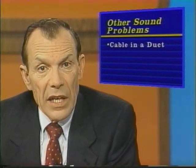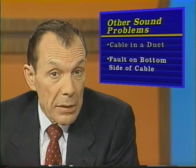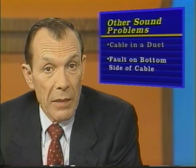Remember that sound waves travel out of the cable at the exact spot where the thump takes place. If the fault is on the bottom side of the cable, the sound waves have to reflect off the soil below the cable before they can travel back towards the ground surface. Since some of the energy will be lost when the sound wave strikes the soil below the cable and reflects back towards the surface, in this case, a thump will be harder to hear above ground than if the fault were on the top side of the cable instead of the bottom side. It would be even harder to hear if the cable were in soft soil, since soft soil won't reflect the sound as well as a more dense soil.